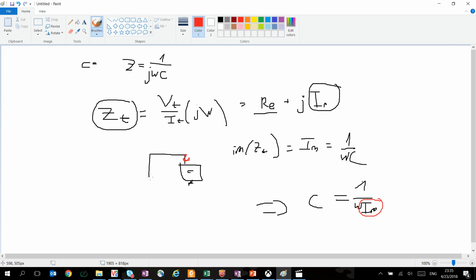The way to do this is basically using the same technique that we've just done, putting the circuit into some DC operating point, and then just measuring the input current instead of the output. And the output of the circuit should also be at some DC point. So either it's going to be floating, like in our open loop amplifier, or maybe you would have to apply some voltage or some load to put it into its correct operating point. And then we're just going to measure the input current.